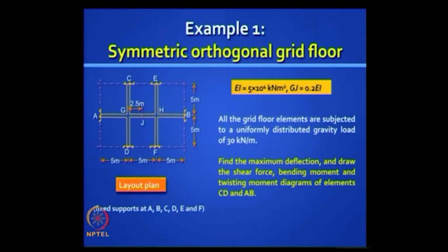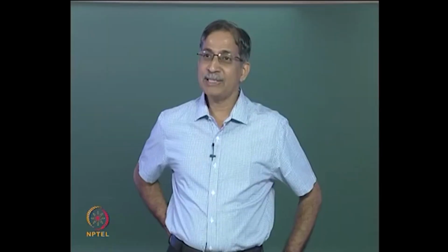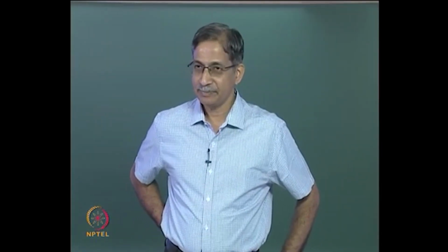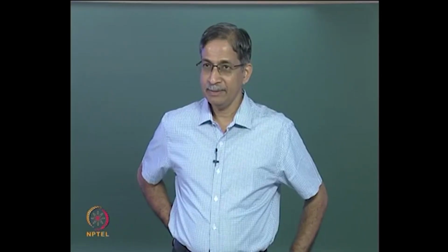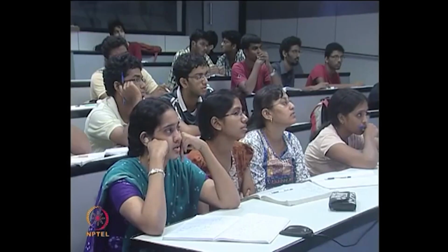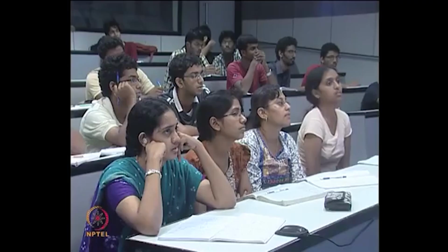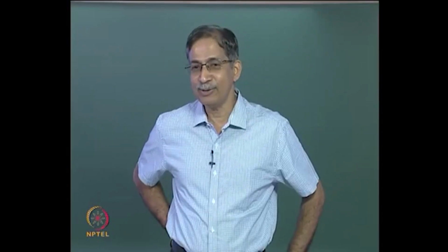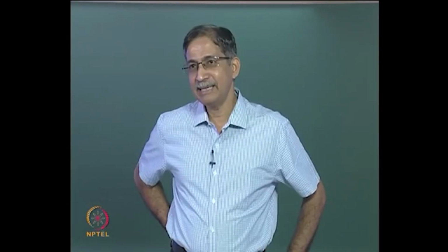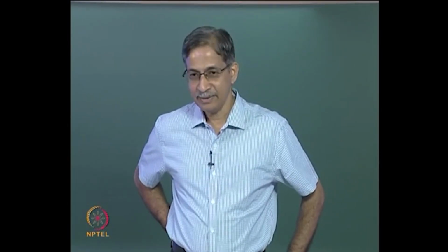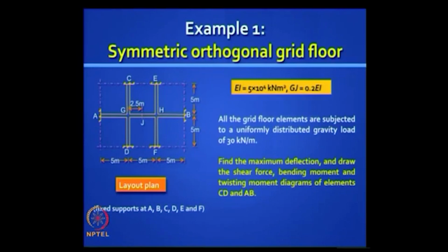You can go one step further and you need not have grid elements for all of them. Which can you replace with beam elements? AB? AB, because you can see that DG and GC are going to be acting like mirror images. So there can't be an angle of twist along the direction AB vectorially, but CGD can twist.